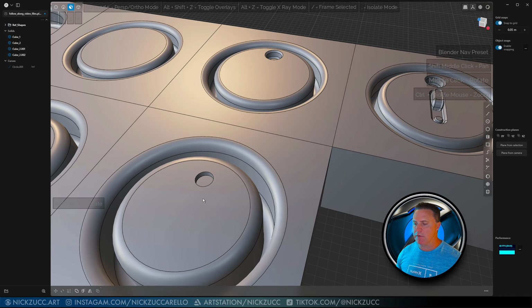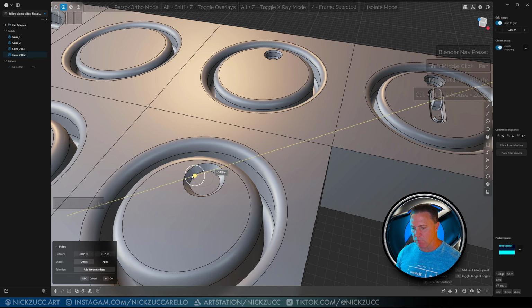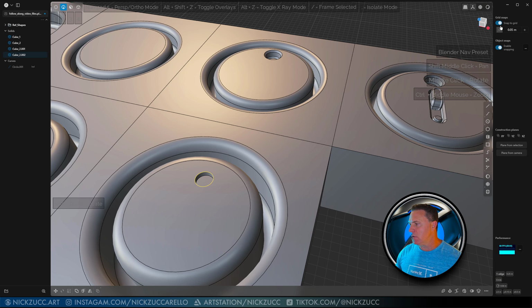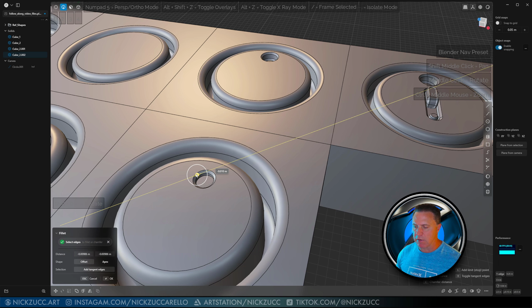Okay, so instead of doing a chamfer or a fillet, we're going to do a chamfer on this one. So if you want to grab this, I'm going to have to hold down Control because I'm snapping to the grid. It also has the ability to snap to other elements on here like this when I'm doing that. So I'm just going to turn off the grid just like that. And then I'm going to tap B to get back into this mode of taking this and then doing this chamfer that we got here.